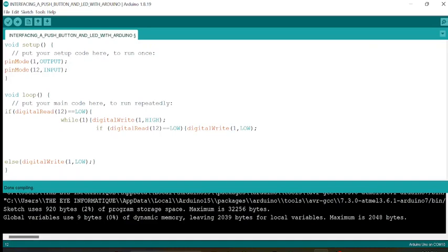So we are putting this in the while loop. It is important that after doing this, we use the command return for the microcontroller to step out of this while loop. That means whenever it detects that the pin has been pressed again, it turns off the LED and steps out of that while loop to begin testing again if we press the push button or not.